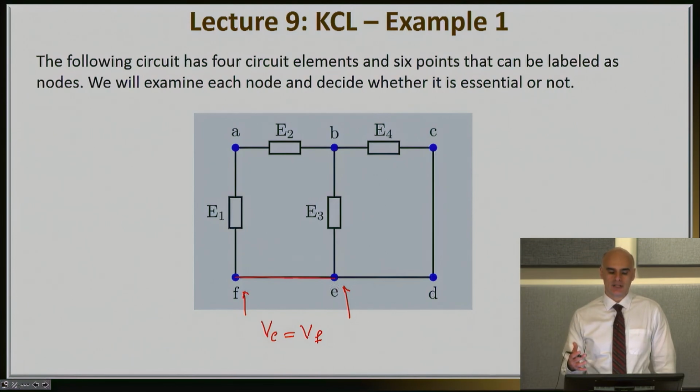So if I wanted to do things correctly, I would not have given F a name. It would really be E. And for exactly the same arguments, node E is exactly the same as node D. So I would rather not label this a separate node, D. This really adds confusion, and it's really one and the same node. And following exactly the same logic, here's one more short circuit that essentially connects directly nodes C and D, making VC the same as VD, and therefore, once again, I don't like labeling this with an extra letter since it does not represent a different electrical connection.